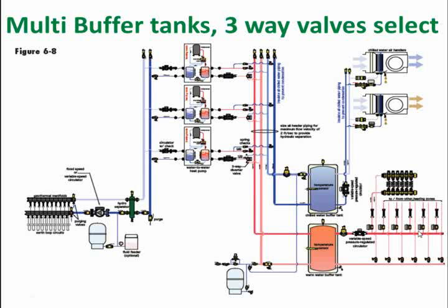All right, let's take it a little bit further, another step further. So now, again, we still have multiple heat pumps in here, and we've got what's called a four-pipe system. So now we've got the ability to store hot and cold water, chilled water and heating water at the same time. So we've added two buffer tanks to this system.